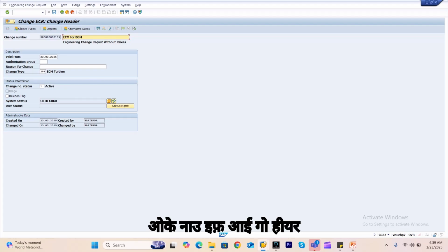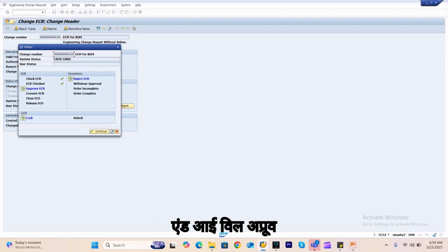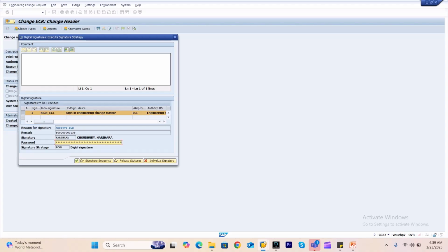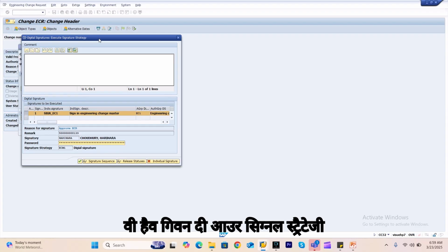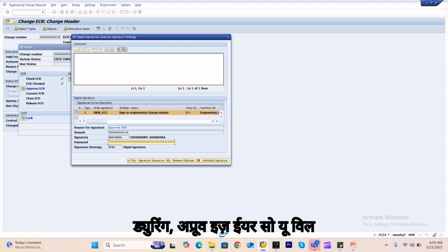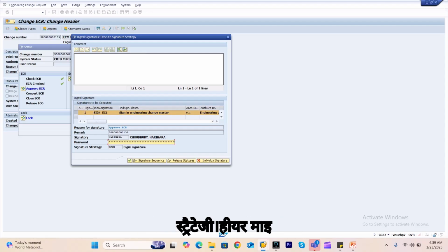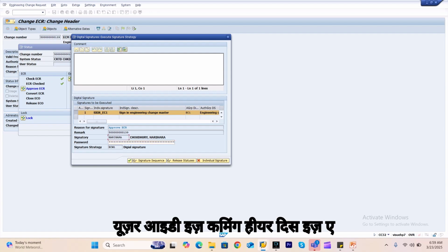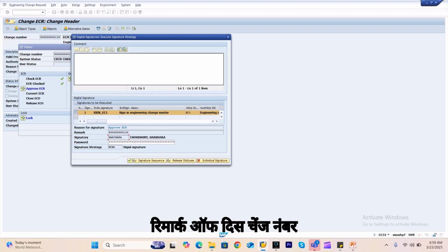I'll save it. Now if I go here and approve, we have given our signature strategy during approve ECR, so you'll get this screen, signature strategy. Here my user ID is coming, this is a remark of this change number, and here if you want to give a comment you can.